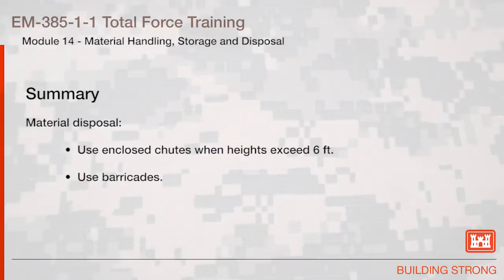Material disposal. Use enclosed chutes when the heights exceed 6 feet. Otherwise, use barricades.